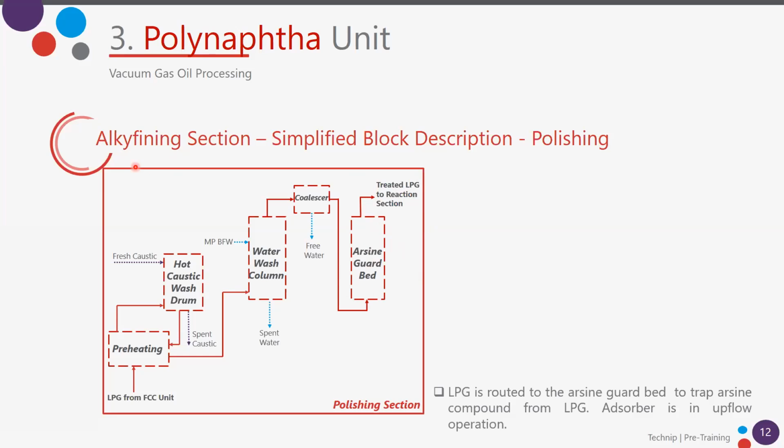So we have here treated our feedstock first, and then we will send it to the reaction section, okay? We have removed the sulfur, we have removed the oxygenate, the nitrogen compounds, the arsine. So now the feed is ready to go to the reaction section, okay?